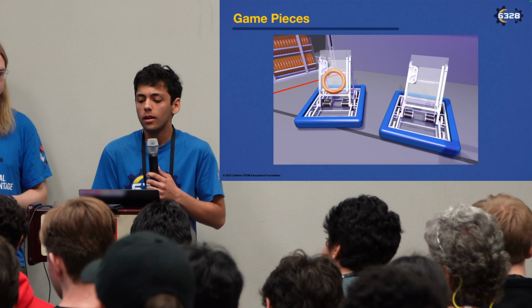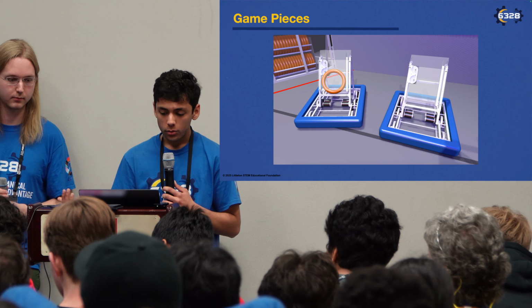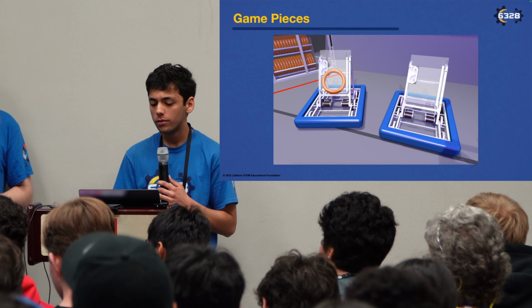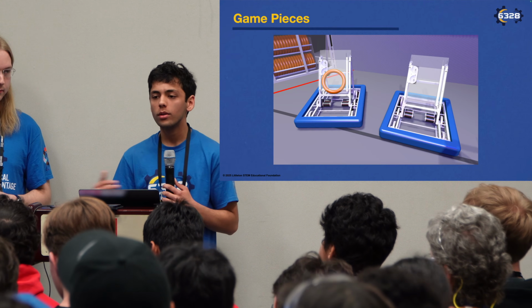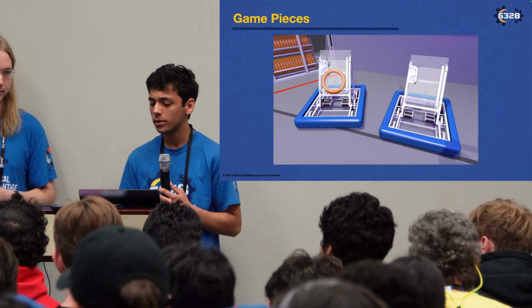It can also be a simple implementation. As in 2024, this is visualizing the note in the kitbot. And all we have to do is publish a single pose from the periodic method of our indexer to show where the note is at all times. And for example, we might implement how the robot knows whether it has a game piece by just using whether a proximity sensor is tripped or not.